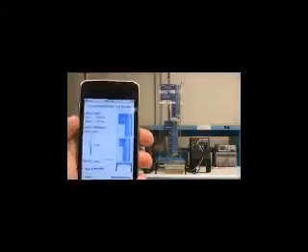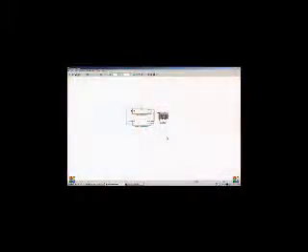Using another iPhone application, which contains an animation of the experiment on the right-hand side of the screen, we may use either sliders or a text input box in order to choose a desired water level in centimeters for the lower tank. After pressing the Start Experiment button at the bottom of the GUI, the Simulink model receives not only the reference command with which to regulate the water level, but also a message telling the controller, located inside of an enabled subsystem block, to activate.